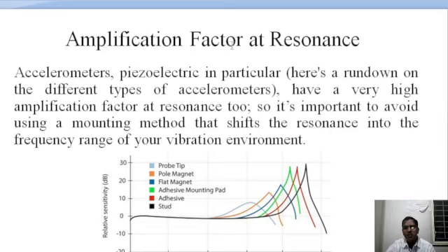Amplification factor has to be taken care of while selecting the mounting method. Accelerometers, piezoelectric in particular, have a very high amplification factor at resonance. So it's important to avoid using a mounting method that shifts the resonance into the frequency range of your vibration environment.